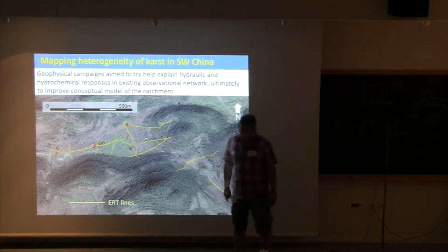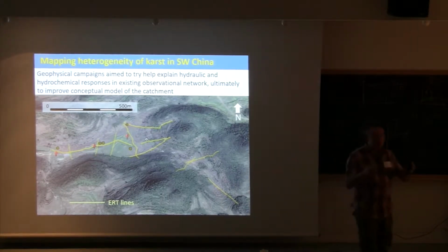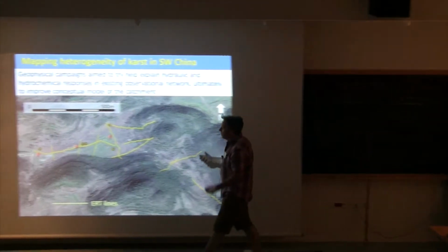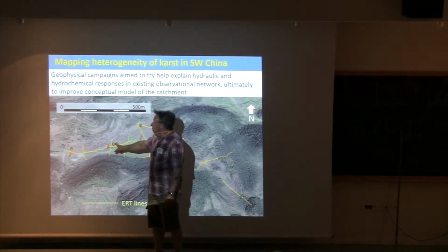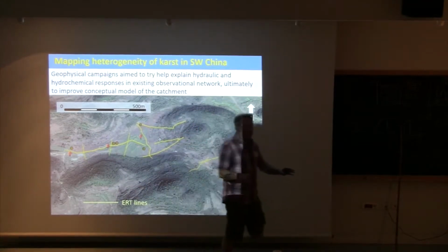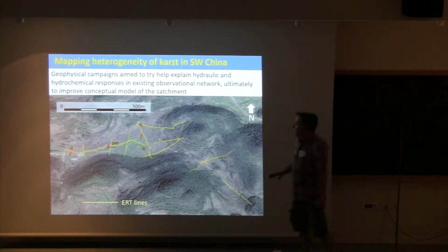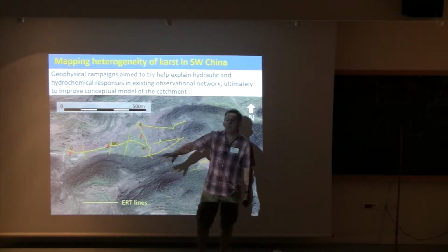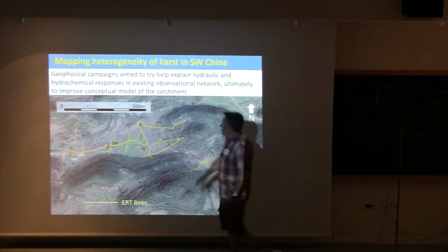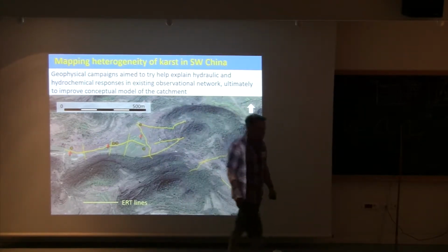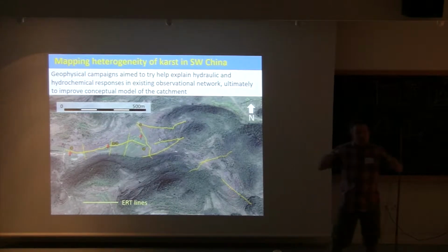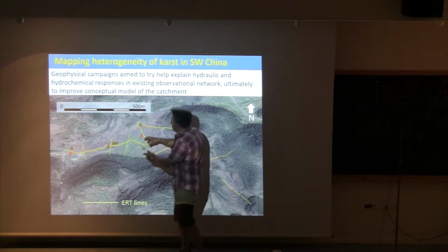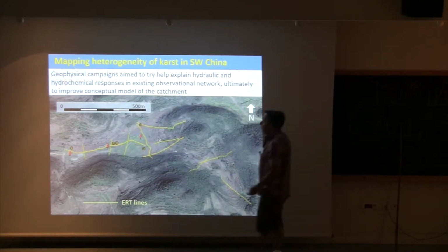There are some springs. And they'd done these measurements in these wells, but they were really struggling to figure out why it is that, for example, here I've got an artesian well, and then 10 meters away I've got a fairly dry well, certainly not artesian. Why is it that this well here responds with a very damped water level response over time, whereas this one shows more of a confined response? So this is the problem with these conventional measurements. We have these point locations, and we need to understand some of the connectivity between them.